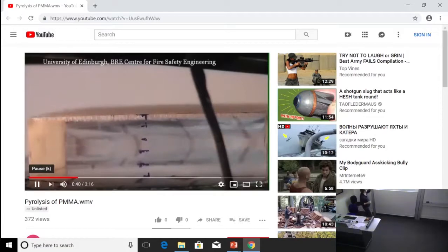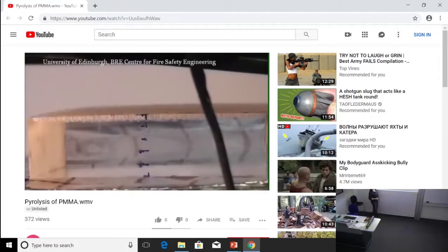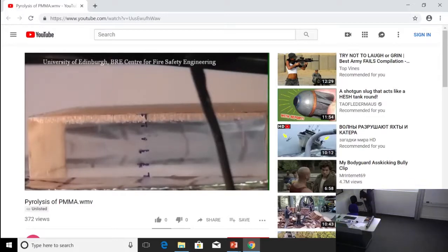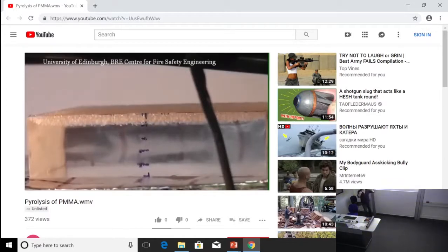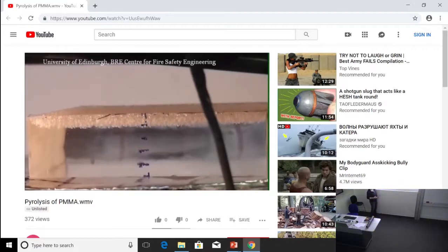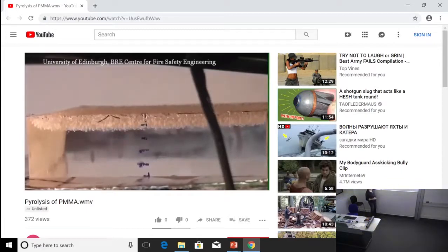Also, you can see the little bubbles. This layer over here that has changed its color are little bubbles of PMMA that are undergoing pyrolysis. And PMMA, when it undergoes pyrolysis, becomes MMA. So poly-MMA, when it breaks down, it just produces MMA, methyl methacrylate. You can see the layer is growing, but also the top layer now is disappearing. That PMMA is literally going away into the lab, into the extraction fume, and outside into the city.